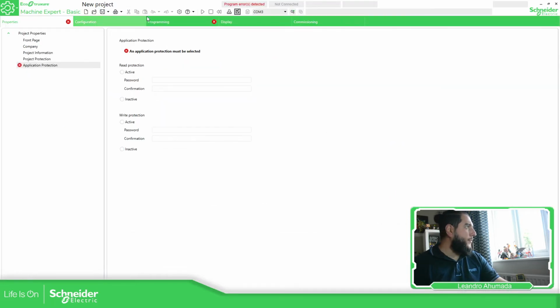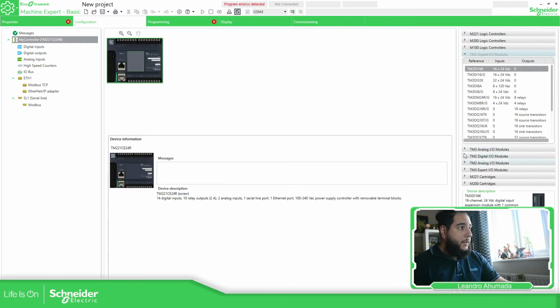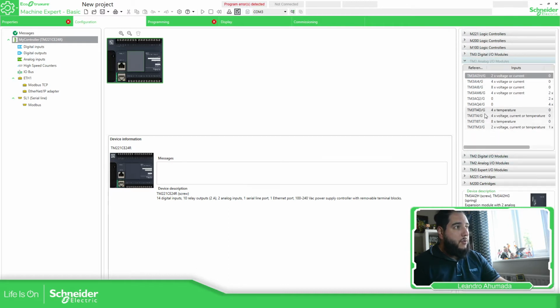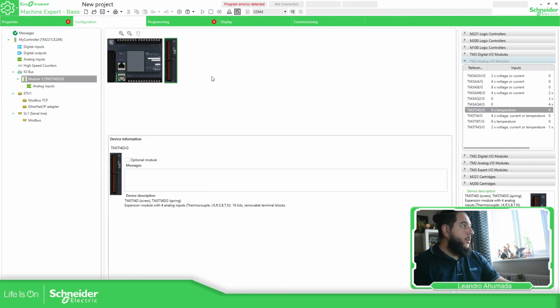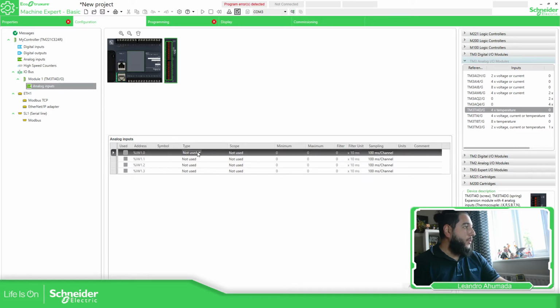So if you are using directly the analog input that you have on the controller, let's say that you are reading temperature, and then you just need to select one of these temperature types that you have. You need to check which are the characteristics of the sensor that you're reading. As soon as, for example, you use a thermocouple, you have this minimum and max value, so you will need to convert that on the other side to go from 0 to 100 or 10,000, whatever you want, just to make it easy.